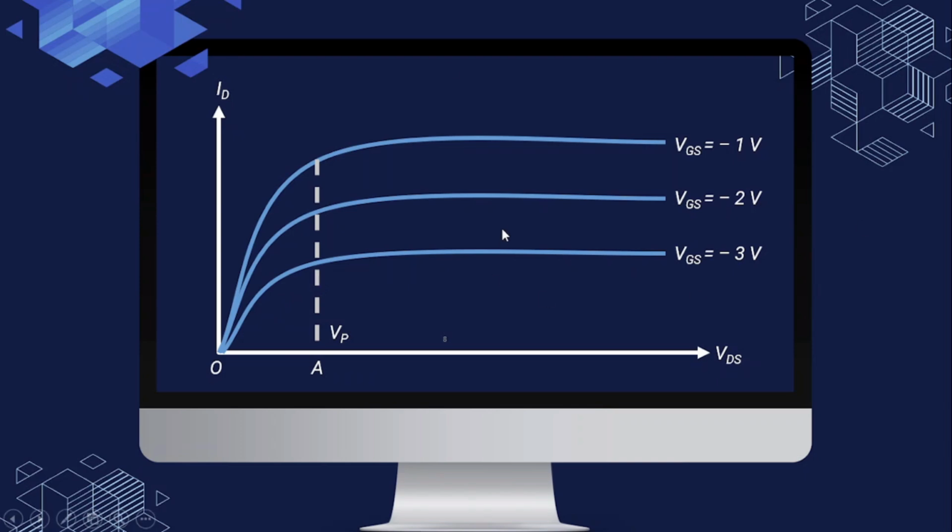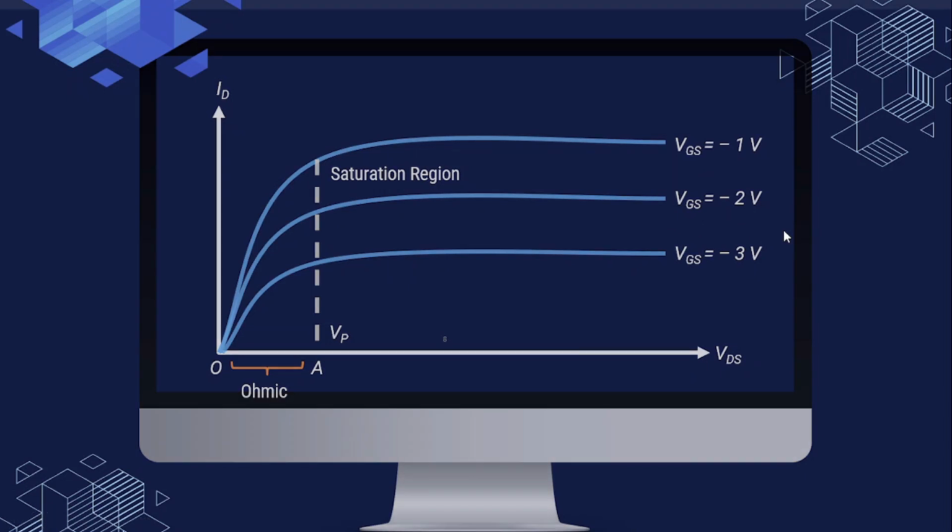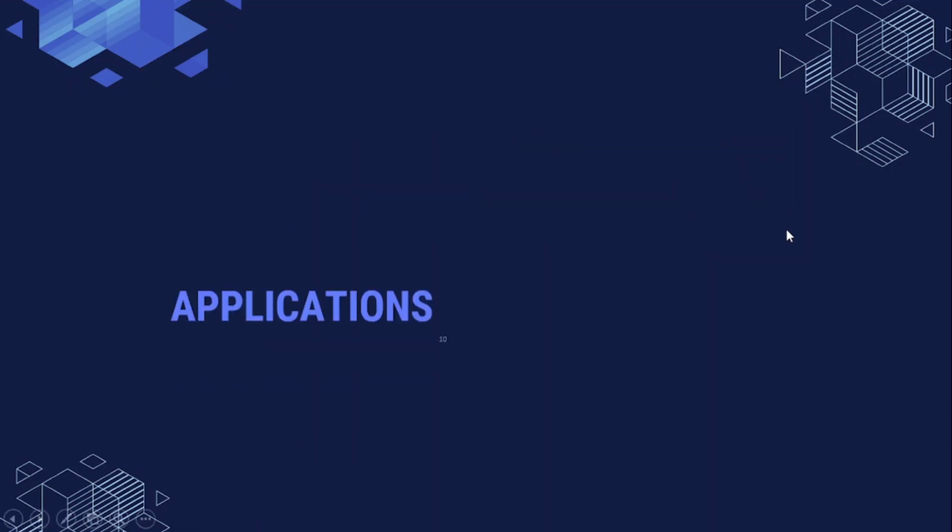This is the voltage at which the channel starts to pinch off. Beyond this point, increasing VDS does not significantly increase ID. This marks the boundary between the ohmic region and the saturation region. The ID becomes almost constant. The JFET operates as a constant current source. Each curve shows a different VGS value: minus 1 volt, minus 2 volt, minus 3 volt and so on. As VGS becomes more negative, the channel narrows more and ID decreases.